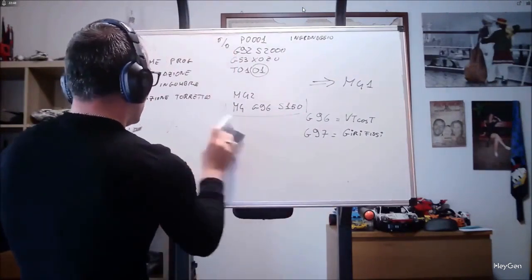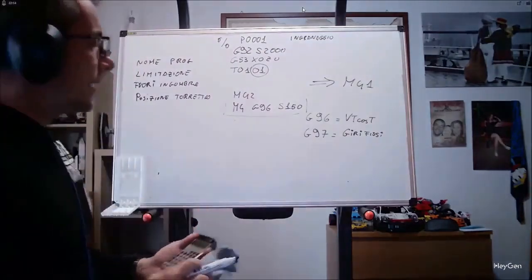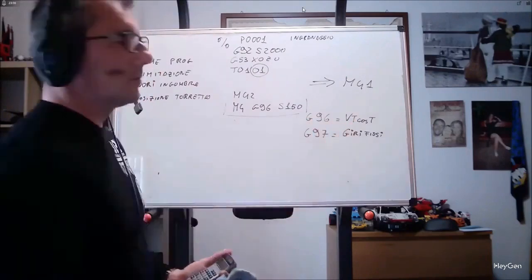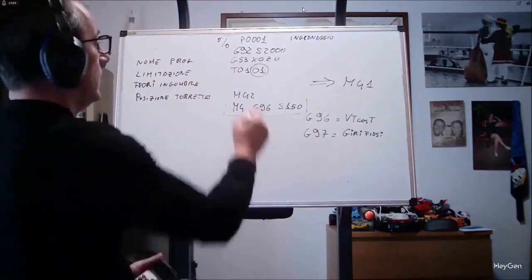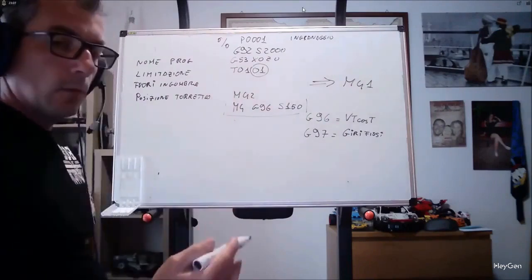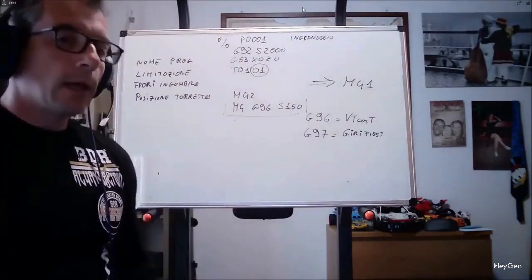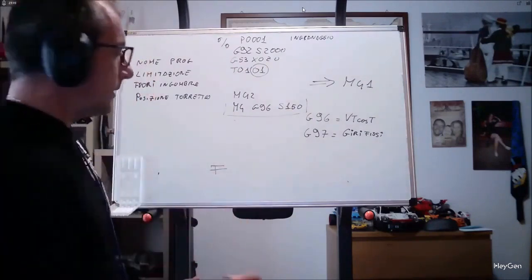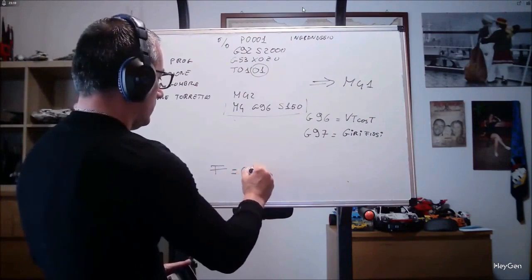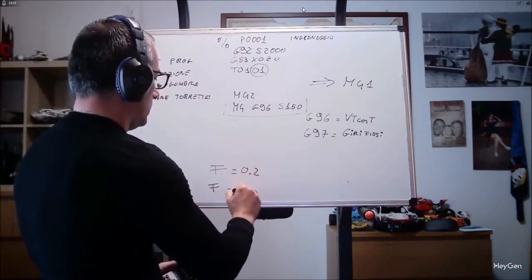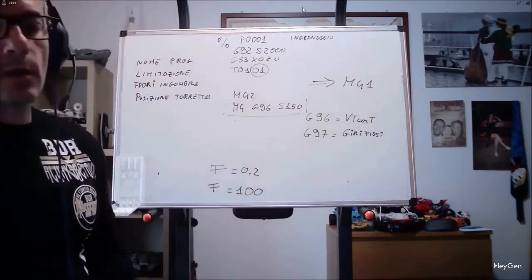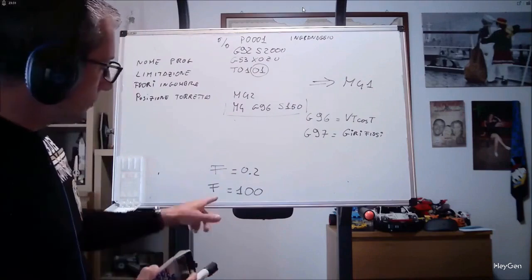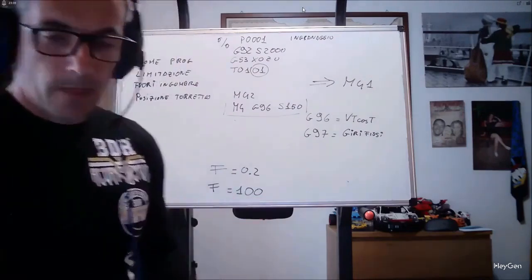Just as we can adjust the way the spindle rotates, in fixed RPM or constant cutting speed, we can adjust it. And we must input it initially, the way the machine reads a feed rate. Later I will teach you that through the F function we will input the feed rates. You will find in your programs in turning wording of this type. In milling, you will find very large numbers.